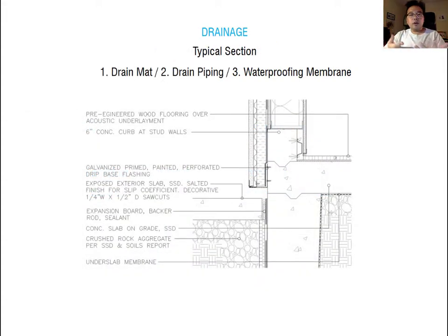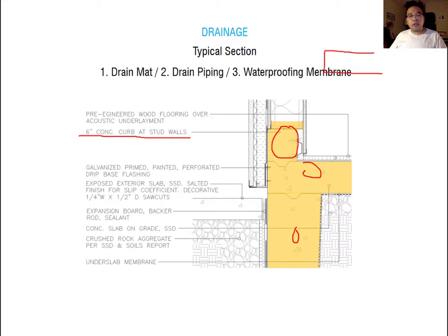So now I just draw out the simple underground and ground condition detail wall section. I'm explaining how you design and consider the foundation and ground condition design. First, you have to understand the design of the main structure. You can see the footing here on the bottom, and then this slab. And then I'm also adding a 6-inch concrete curb here. It's not necessary. Simply, you can add the concrete and you can add some metal stud over it.